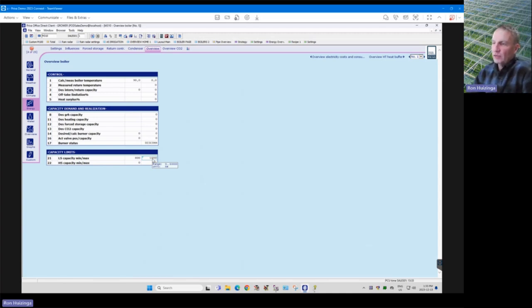But 5,000 is a typical smaller boiler nowadays for the vegetable greenhouses, I would say. The boiler can vary in capacity from 0 to 100%. At the lowest flame rate, it gives about 800 kilowatts, and at the highest flame rate, about 5,000 kilowatts.